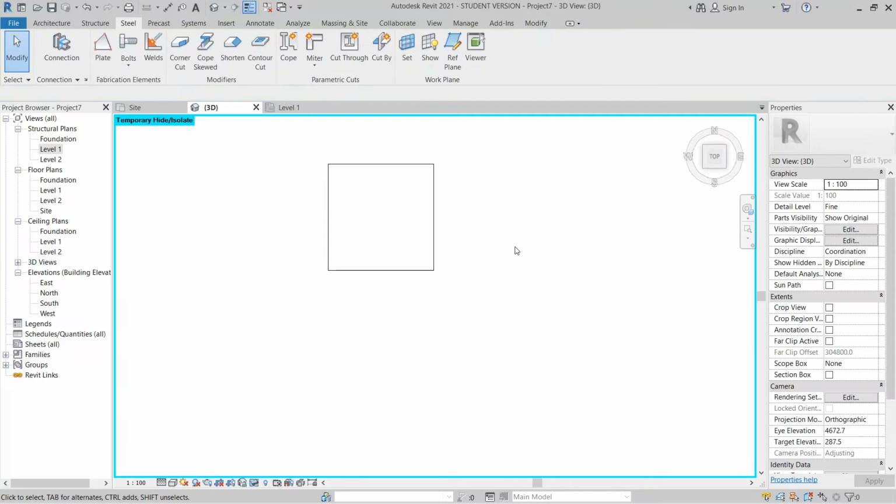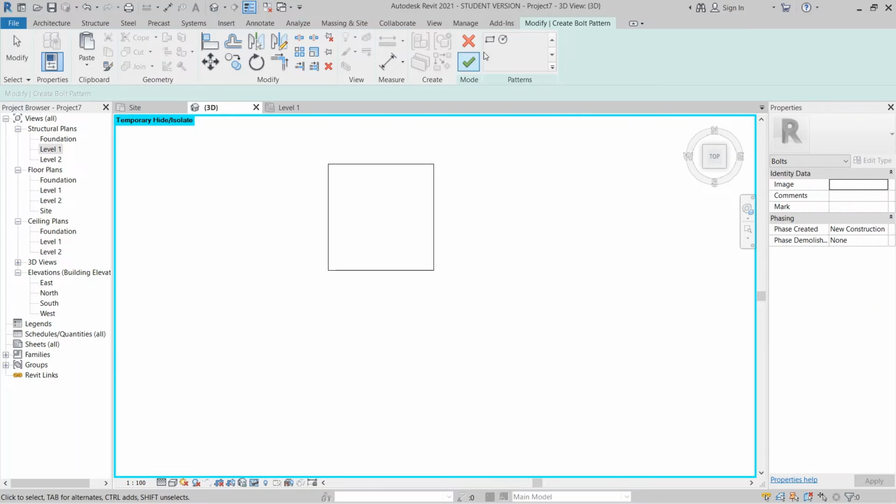Okay, so I just hit escape first, go to my steel again, go to bolt and nut here, select this one, go to bolt and nut, and select my steel plate here, hit enter on your keyboard, and again we need to select here. After you hit enter, you might need to select again for the top one for the whole structure, then adding for rectangle, start here like this one, and I just hit finish first.